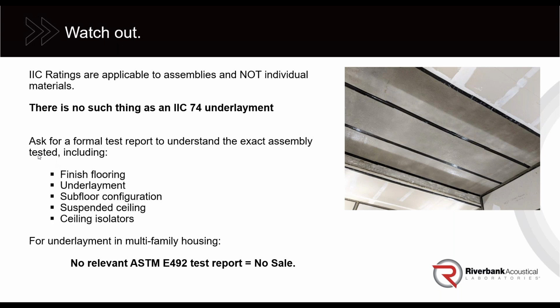You will sometimes see, maybe if you go into the big box store, an underlayment with a label on it that says IIC 74, let's say. So the question one should ask is, well, okay, what was the assembly that was tested? Because this IIC 74 doesn't tell me anything. In fact, it's a clue that it was probably a pretty substantial assembly.